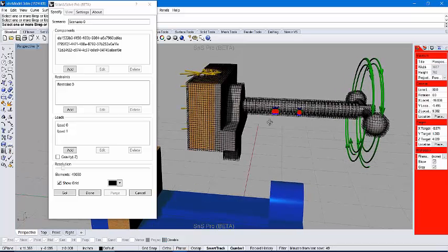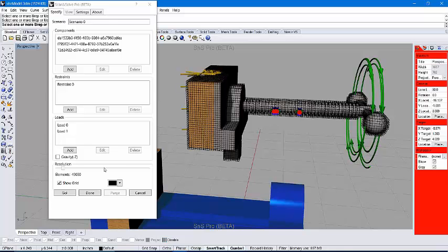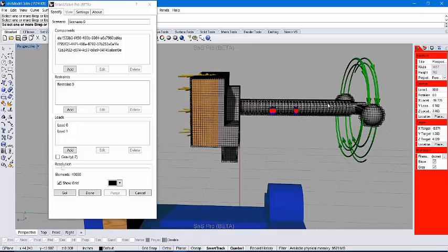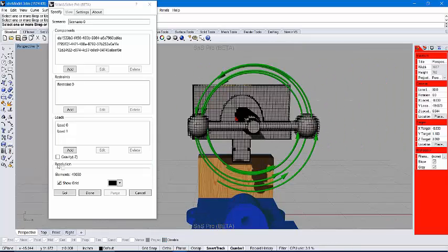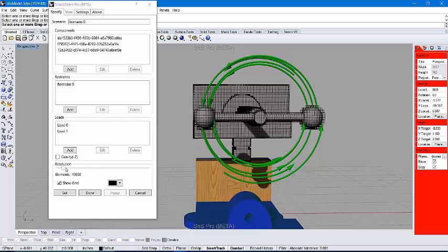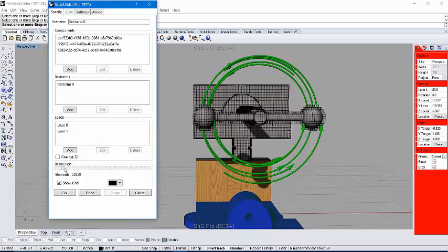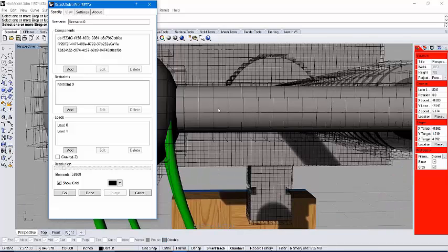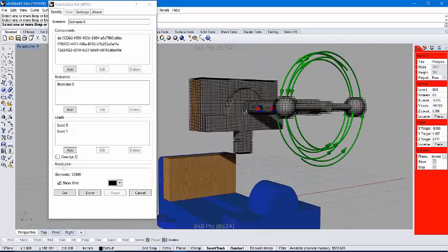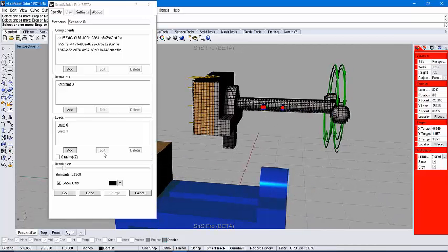A general rule of thumb is to analyze the grid and find some of the smaller cross sections that you're simulating on, and make it so that the grid has about 3 of these elements per given cross section. So this looks pretty good. It doesn't have to be exact; just about 3 is a good general rule of thumb. So this simulation is now ready to run. Typically, I would click Go and let it load. However, I have already ran the results, so we do not have to wait for it to load.